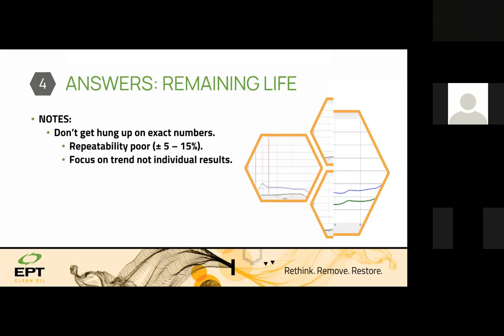And just about the LSV ruler test, which works on the antioxidant levels, and RPVOT, we need to know that repeatability is very poor. It means you can get an oil tested and get 90% additives left, antioxidants, and the same oil, same machine, same operator, test it again, and it jumps up to 95%.